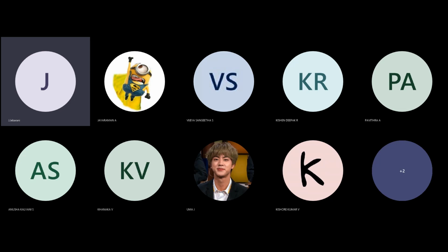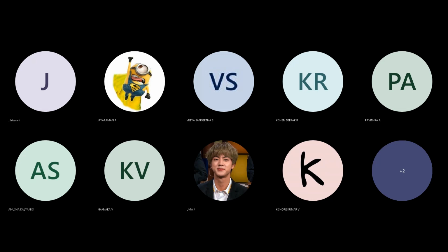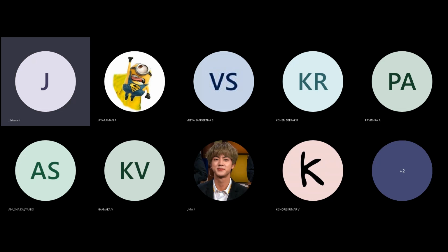So when compared with the gas assisted injection molding technique, here the polymer is filled in the mold section, and then the water is introduced into the mold section, and the water is evacuated by gravity or air. In the short shot approach, this process is also called the bubble process or blow up process.